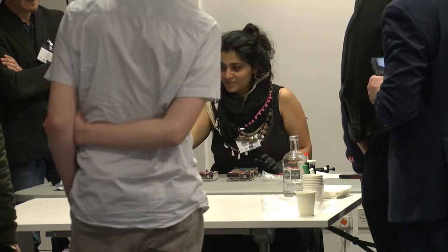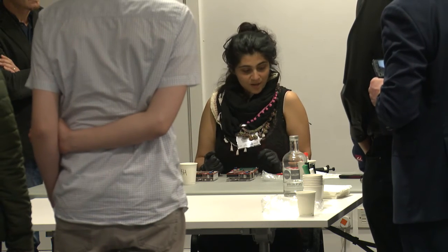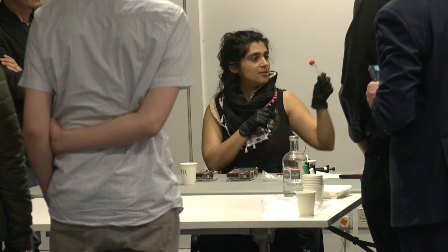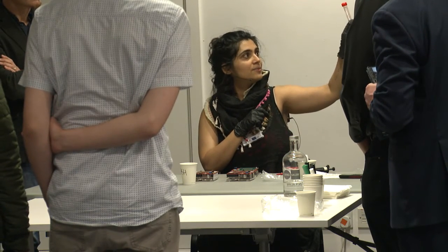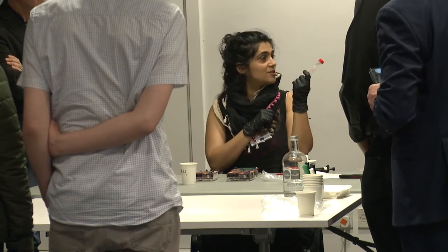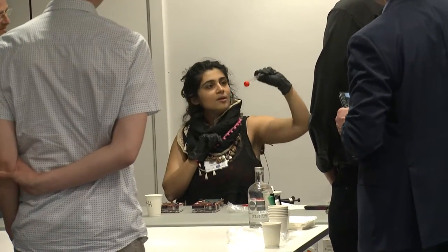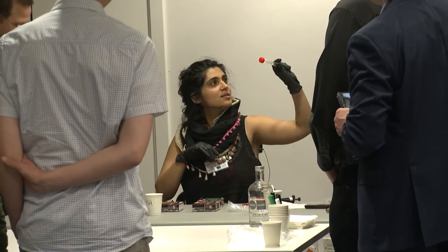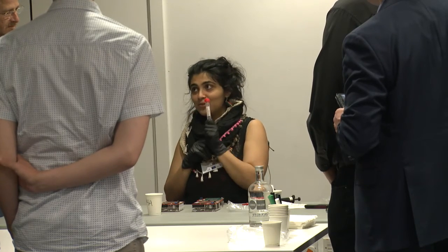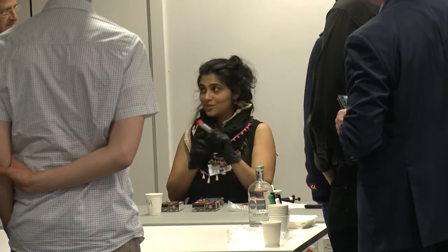Now, the foil is the insulator and the dielectric. We are coating it on top with silicone oil. Silicone oil is a very low viscosity oil, lower than water, but there are also about 400 types of silicone oil. So the viscosity matters a lot. Remember that the force that we have there is surface tension between what we have in between. And this is silicone oil 5 cSt, so viscosity is 5. It's really important. If you use 1, it doesn't work. If you use 250, it doesn't work. Viscosity is very important.